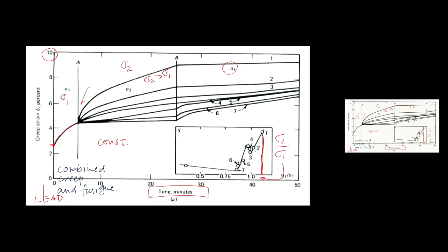So what if it's not greater than 1? What if we're just holding the same stress? What does that look like? Well, if we hold the same stress, then there's no change. The ratio is 1.0, and we're at line 3. So line 3, I'll highlight it here, is a nice continuous line. It doesn't really have that accelerated rate, right? It just continues on with its logarithmic decay. Okay, that makes sense. And then there's a line in between.